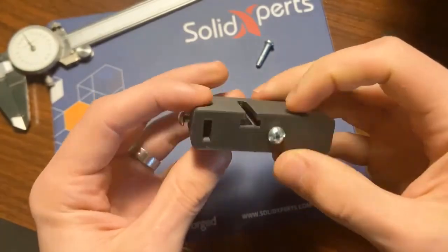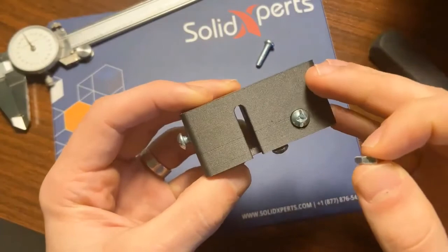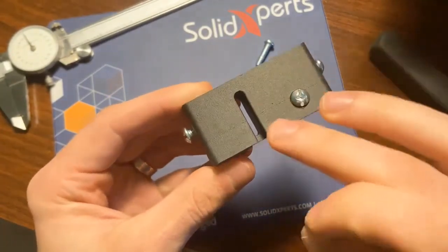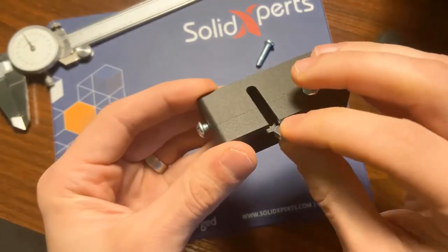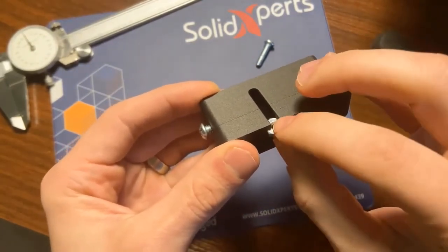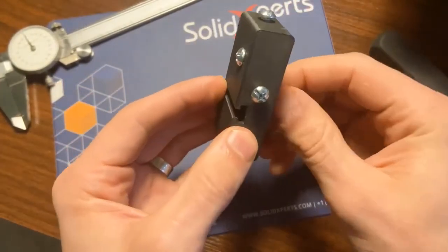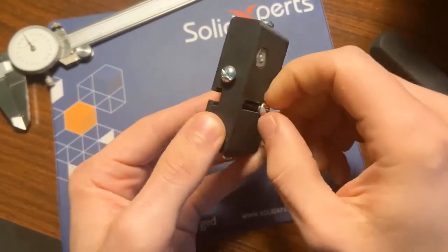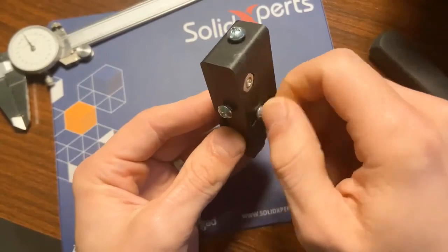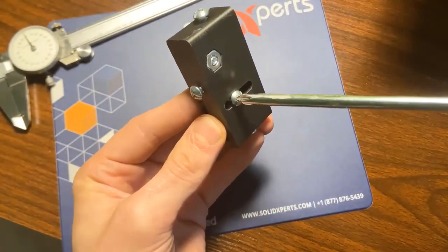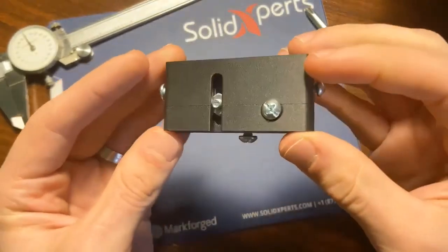And last example is that you can have a small channel such as this with an opening where you can drop a nut in. You can drop it out as well, but it has the flexibility to move up and down with a hole in the slot on the other side. So I can drop this inner slot, point down, add this here, and we can adjust this up and down as needed. Apply tension and tighten. And there we go. So a couple different examples of embedded fasteners.